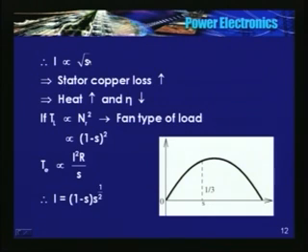So as S increases, stator current also increases, and therefore stator copper loss increases. So there is an increase in the stator copper loss, there is an increase in the rotor copper loss, therefore there is an increase in the heat developed, and there is a reduction in efficiency.